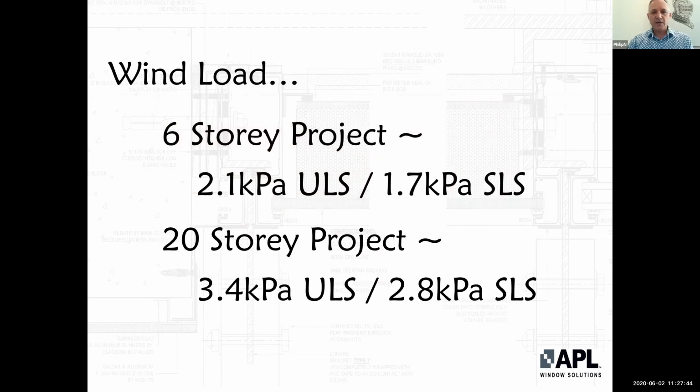By contrast, just to give you an idea of the sort of wind pressure you'd expect if you're building a 20-storey project, you could get wind pressures up to 3.4 kPa ULS. As I say, in New Zealand, you probably wouldn't get much over 4.5 or possibly 5.